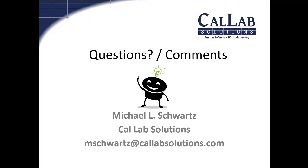There's something new about the relative spec, because I thought they were looking at the drift and stability if you referenced it against something in your lab. Yeah, if you take that relative spec and then take your calibrating standards and calibrating process and RSS that together, it isn't a straight addition, because an RSS is the practical accepted way to combine multiple uncertainties like that, when they are independent. So you don't add it together, you RSS it together in most cases. That makes perfect sense.